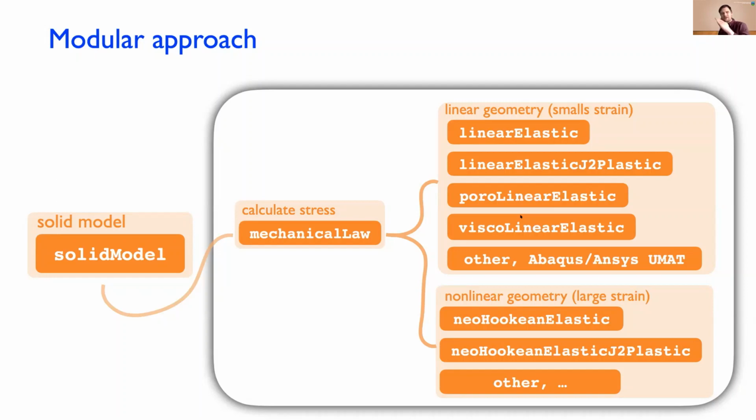If you really want to specify the individual plies and their directions, I know, for example, Abaqus has a composite layup tool that lets you define all of that and calculates the equivalent properties. So that's not available, but in theory, you could implement it if you really wanted it.